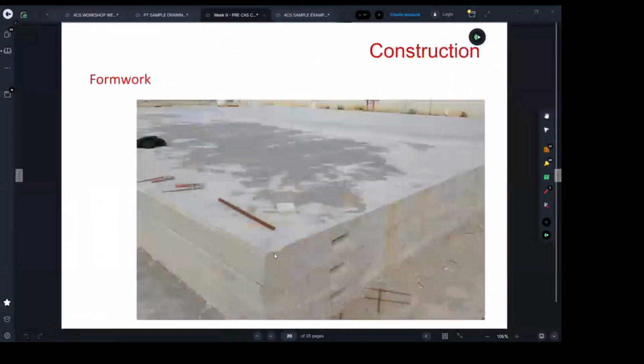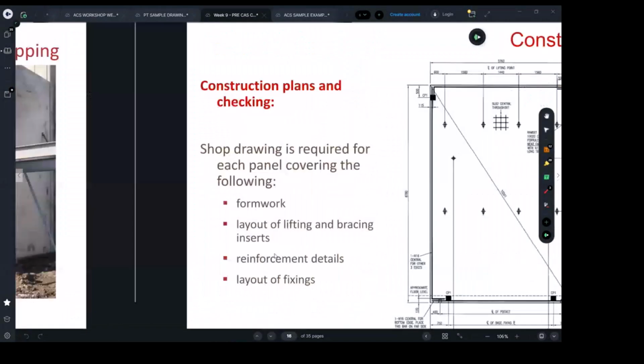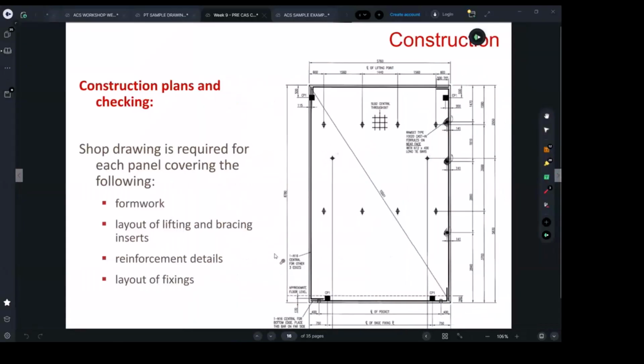So usually those shop drawings don't only give dimensions, and don't only talk about the structural engineering features and the architectural features. They also talk about details that will help you make very important and costly decisions, for example the crane type and size you need to have for the site. That's basically what I was talking about.